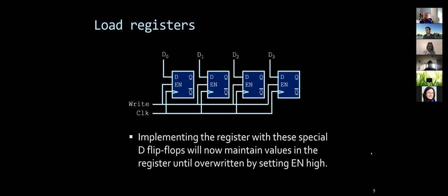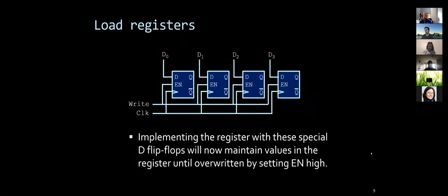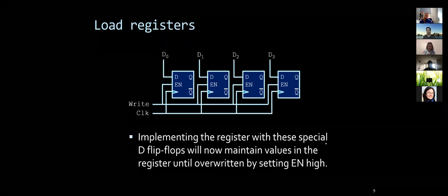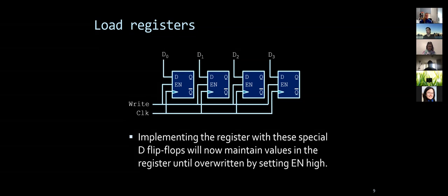Okay, you see the difference, right? In the previous design, you can only do one thing. You can design one flip-flop that would either write the value or read the value. It cannot distinguish. So there is just no information. We built flip-flops that do one thing or another, or invert, like T flip-flops that invert the value, but we need a smarter flip-flop that has the ability to read when needed and to write when needed, and that we just did, right? Okay, I hope everyone got it.